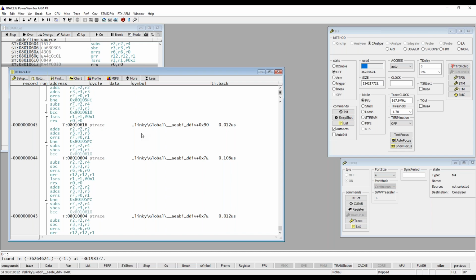And of course, this is normally not done by hand. Maybe you have some automated testing that runs on your target, and then you can use the APIs in Trace32 to control Trace32 from a Python script or whatever you use as a framework for testing. You can do it from a script, but I'm going to show you just doing it manually and what you can expect of the result.